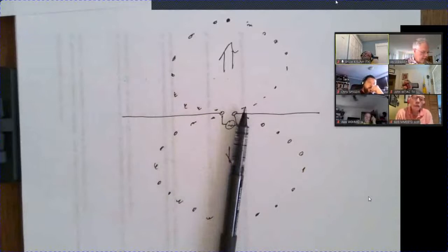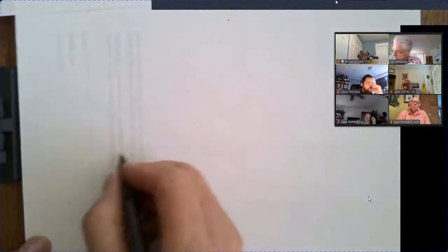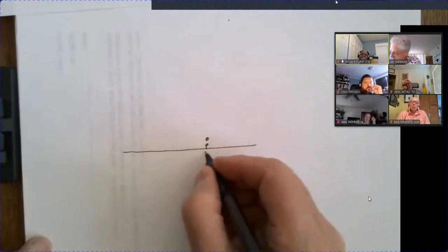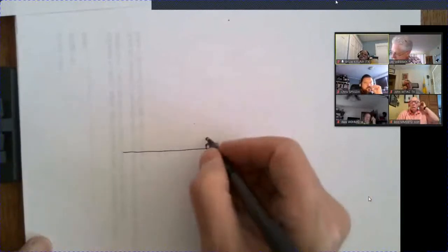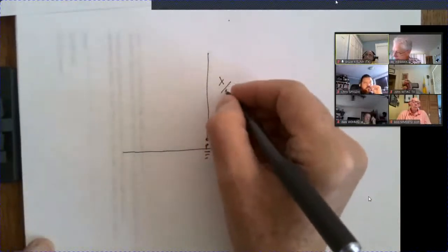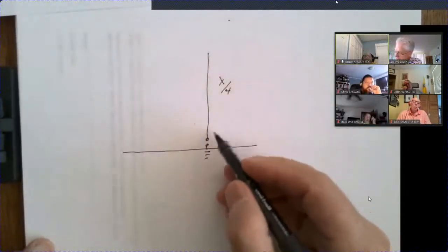That leads also into a number of things which we're going to talk about more here. And let's, by the way, while we're at it, that's a dipole pattern. If we look at a vertical, so we've got a vertical here over a ground. So this is a quarter wavelength. It radiates like a half dipole.